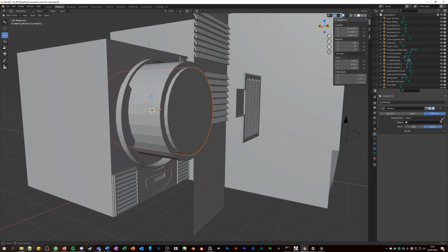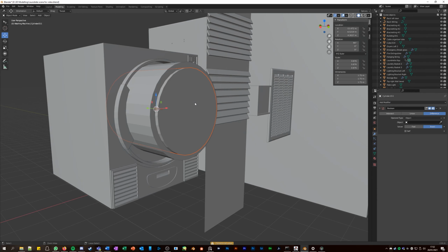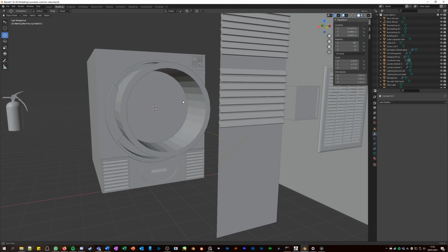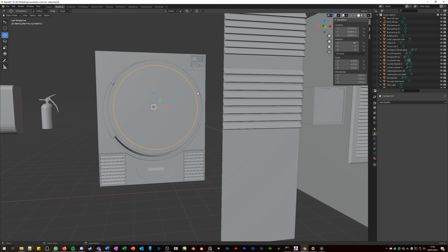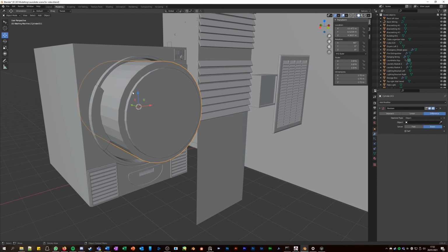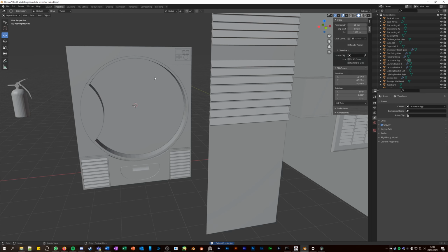So I link these two together with this eyedropper. Oh, I did it the wrong way around. So yeah, there you go. So I link those, and then it cuts out the whole of the other cylinder inside this shape. It creates this metal rim, which I'm talking about. It's just a simple way to create this rim.